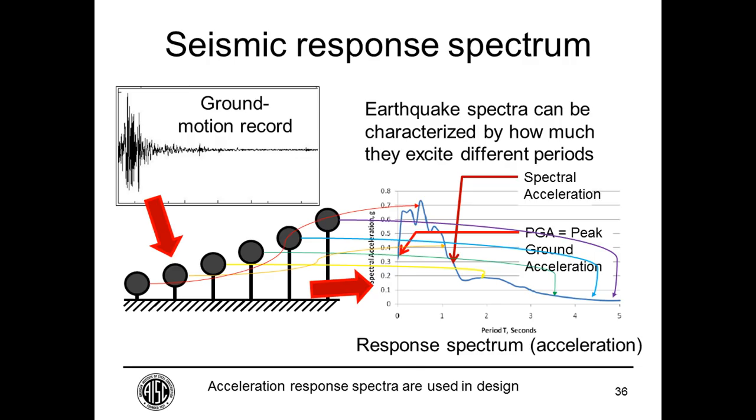And maybe buildings of a certain height tended to suffer, and it just happened to be those buildings that had that natural period that got hit harder than one might expect. So hopefully that addresses the question. The response spectrum comes from data, earthquake data that's been recorded, and we hope represents earthquake demands that haven't occurred yet.